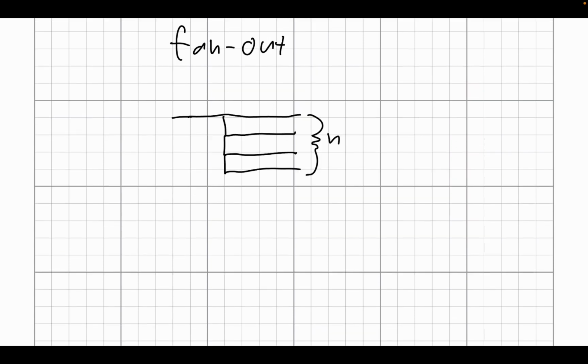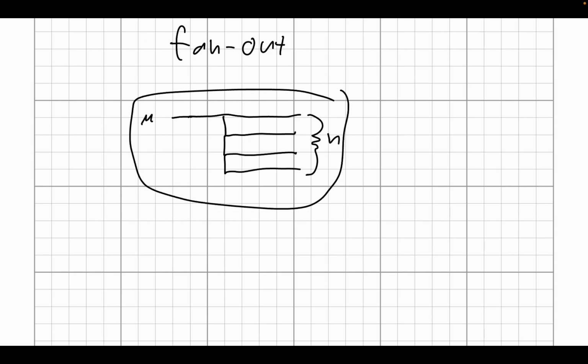Now, the way that this is relevant to the RISC-V bit swiveling magic is that one of the things that we're going to have to do to our immediate for an instruction is that we need to sign extend it. And sign extension is literally doing exactly this, right? You take your most significant bit and you just copy it a whole bunch of times, because the most significant bit is a sign bit, and sign extending, you have to copy it. And because of this, there is actually an enormous amount of fan out that gets generated by sign extending.